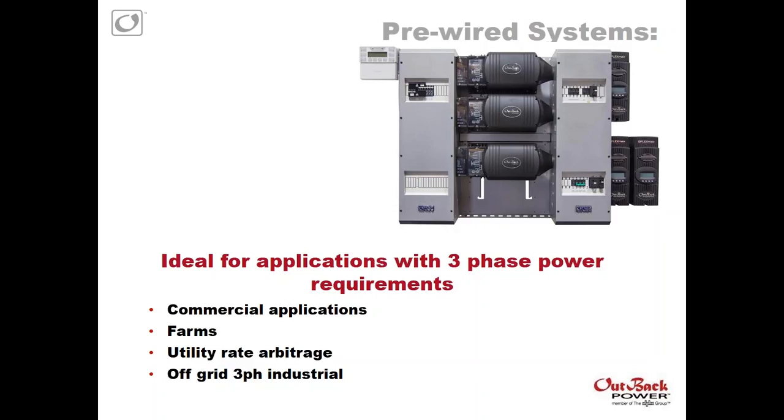With these systems, they do all have a standard 208 volt output. I know that you guys have plenty of 480, 600 different three-phase systems up there. So keep in mind that if you are talking about those, you very likely will need some transformers on the input and the output.